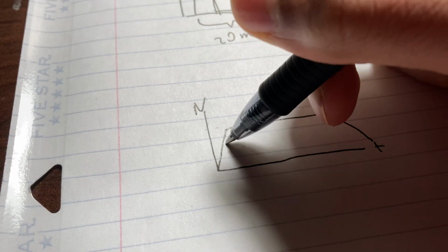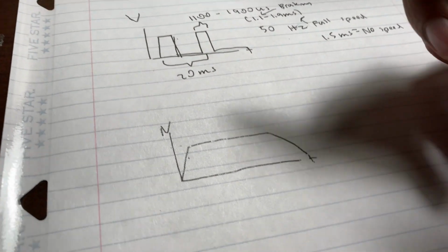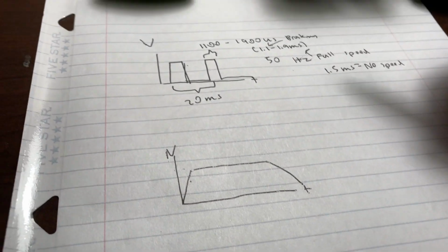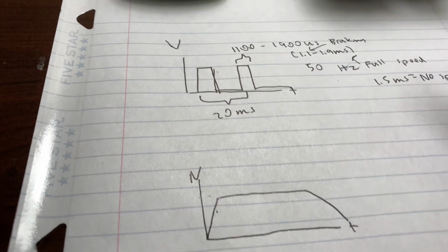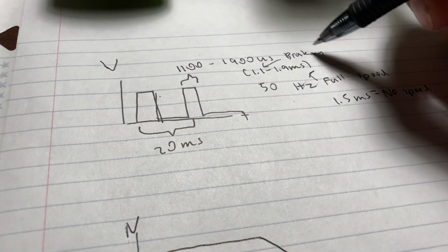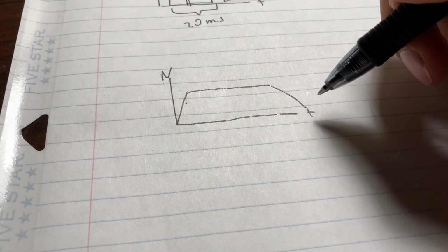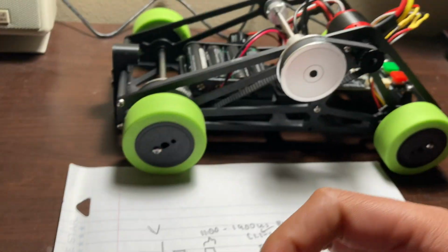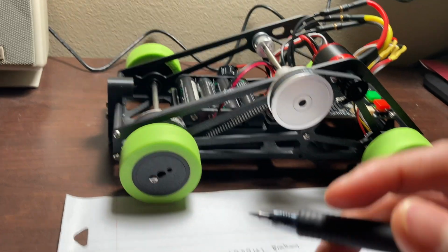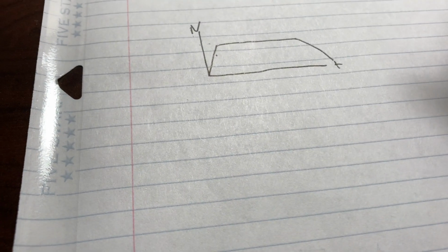So we want to have constant acceleration and constant deceleration. To achieve this, let's start off with the deceleration because that's simple. Let's look at what we're commanding to the motors. We're going to be graphing this PWM signal versus distance, because we really want the motion of our vehicle to be in terms of distance rather than time, since we're trying to go a specific distance rather than execute anything over a specific amount of time.